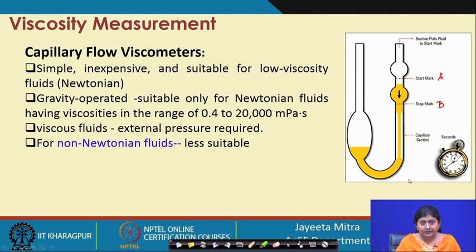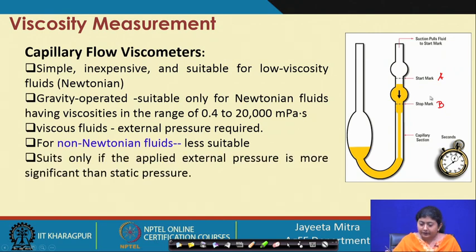So, the shear rate is changing. That is why it is very difficult to measure non-Newtonian fluid. However, if at all we measure non-Newtonian fluid viscosity by capillary flow viscometer, then we apply some external pressure and consider that this external pressure is more significant compared to the static pressure.